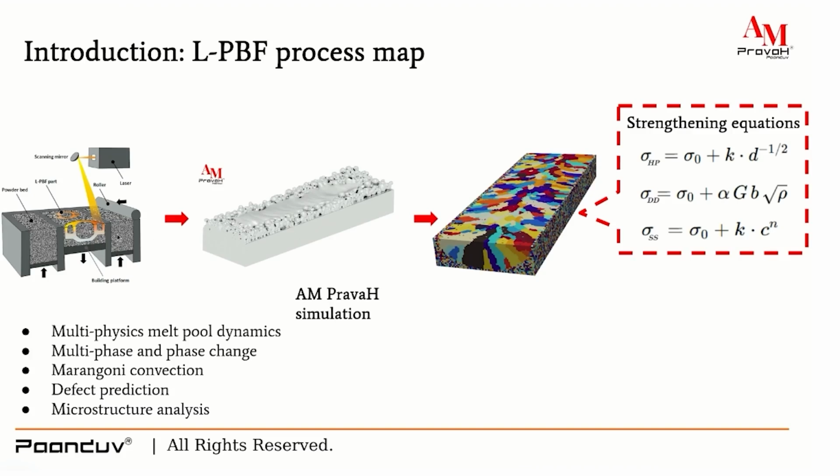If we run the simulation, this kind of process will happen where the laser falls over the metal powder and melts it, and according to the scan speed, it moves further and makes a single layer. It can be single layer, multi-layer, or multi-track. Later, after solidification, we can study the microstructure also. The microstructure will be dealt with in the next session.